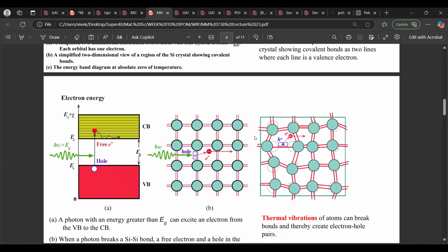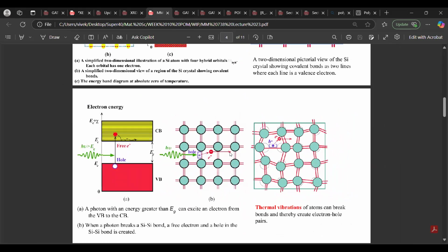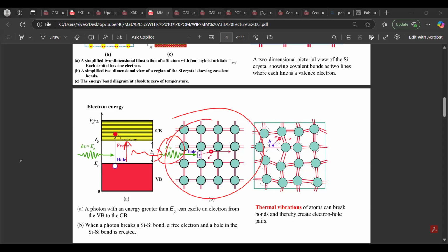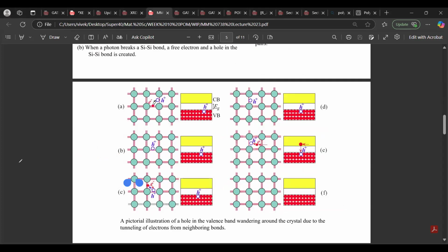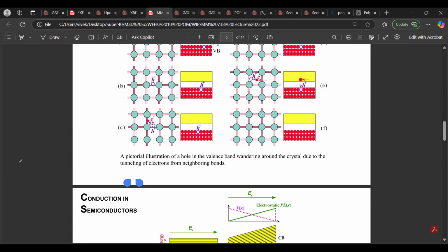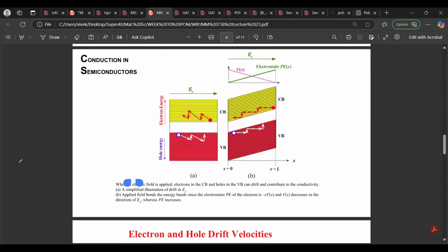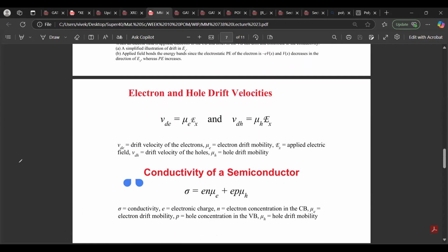So you see, this is all about typical silicon, the silicon matrix, where the energy is getting absorbed and the electron is getting transferred from valence to conduction, and you get this typical transformation and electron transition. Valence and conduction band, how they are connected with each other. How the electron is jumping, how this electron-hole annihilation or splitting is happening. This is typically the band diagram: hole energy, electron energy, all this. And this is v equals to mu E, that we all know, the mobility and drift.